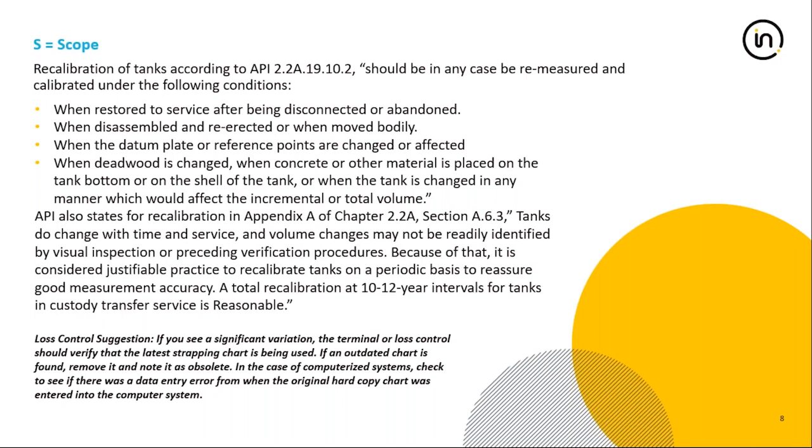The second condition when you should recalibrate your tank is when you disassemble it, re-erect it, or every time you move it.